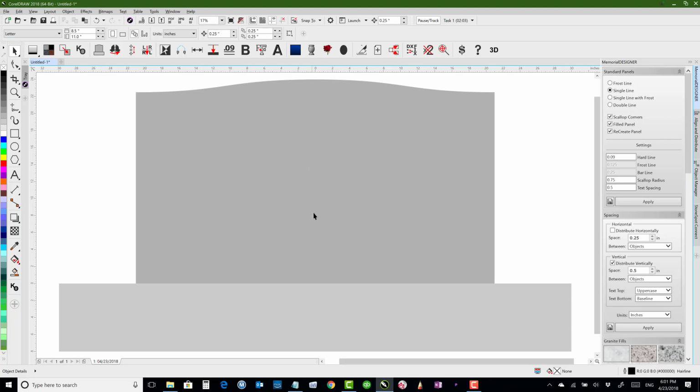It centers it on 0 here, and then it builds it where 0 is also here. So if you are one that likes to use XY coordinates, you can see if I click on the die, it's going to show that it's at 0, 12. And that's because it's actually going off of the center of that. So this center mark is 0, 12.